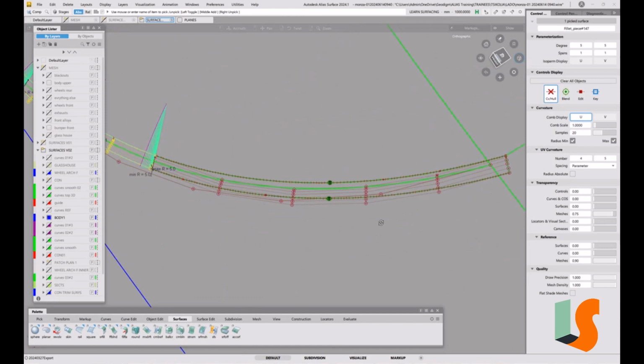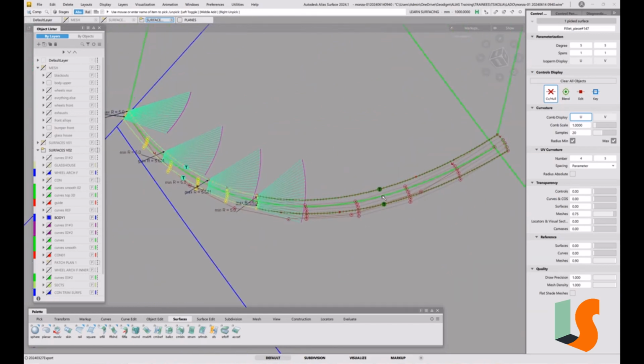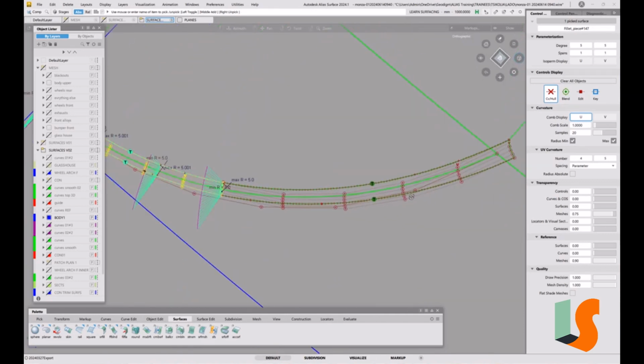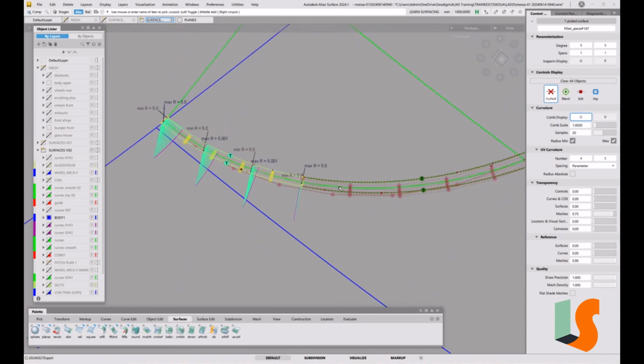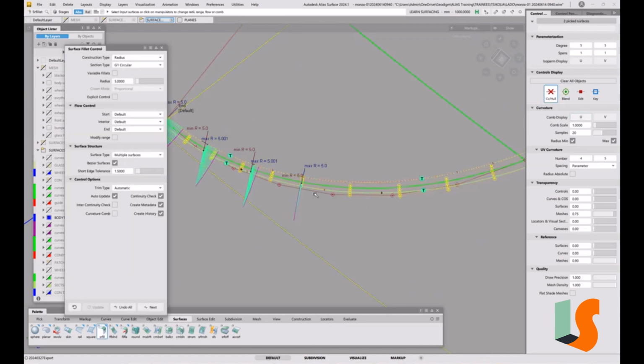Now the thing with having a constant radius is that if the angles of the surfaces change a lot, then you'll see that neck in. You can't see it here. The angle is pretty constant, but it can. You can find that the fillet comes and goes, the edges come and go. Because I've got history on there, I could just go and play with that.